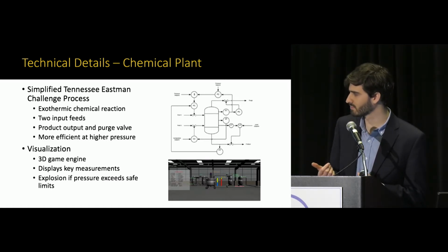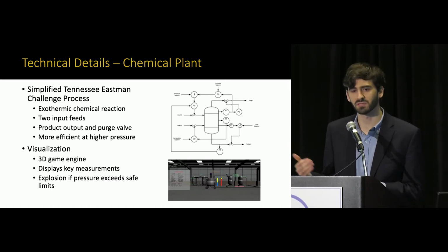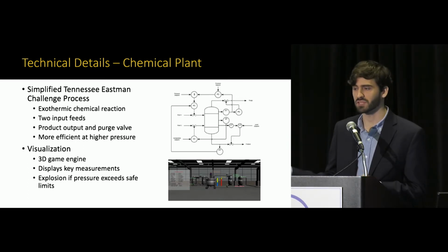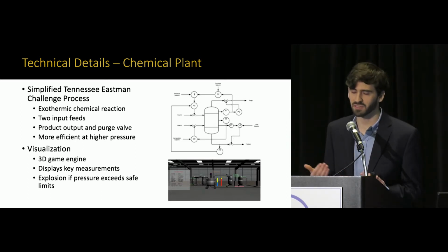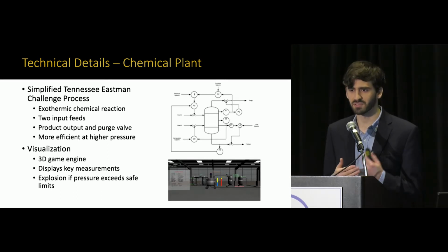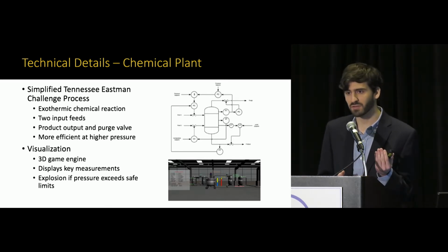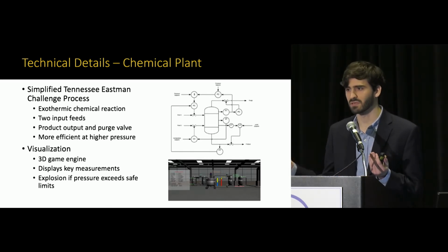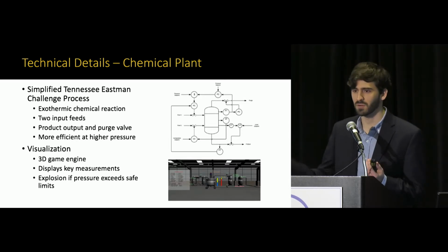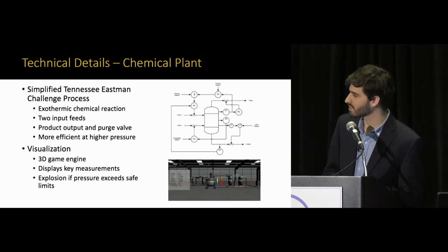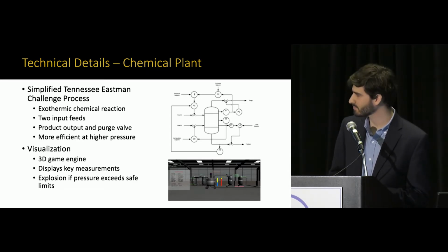The main idea being displaying all those same key measurements that are being shown on the operator's HMI. But if you're practicing, for example, the man-in-the-middle attack, you can see the difference between here's the true values of the process, here's the HMI being lied to. The operators are seeing everything's fine, but in reality, the process is getting messed up. Someone's attacking it.